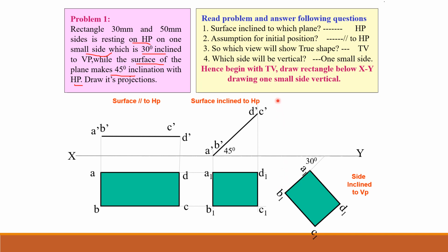I am going to draw the projection lines from A1, B1, C1, D1 towards the vertical plane, and then correspondingly horizontal projection lines from this A dash, B dash, C dash, D dash, and wherever those things are going to intersect, that is A dash line intersects with A1 line, I am going to mark that point as A1 dash. B dash line intersecting with B1, I am going to mark it as B1 dash. This is how I am going to do it. I have drawn the lines and the horizontal lines, and then I am naming these intersection points.